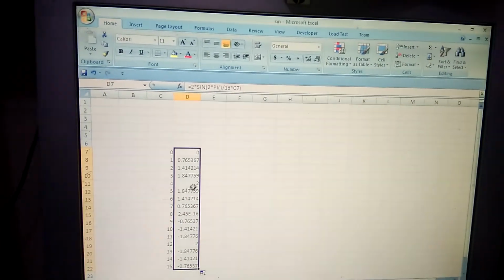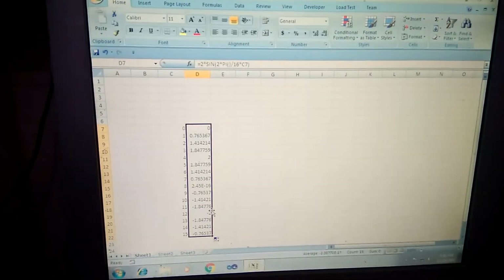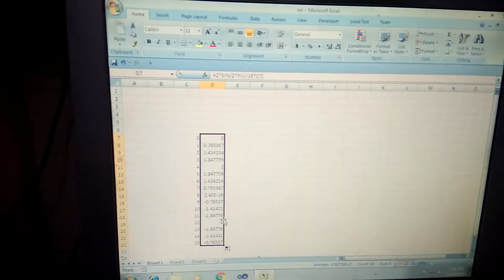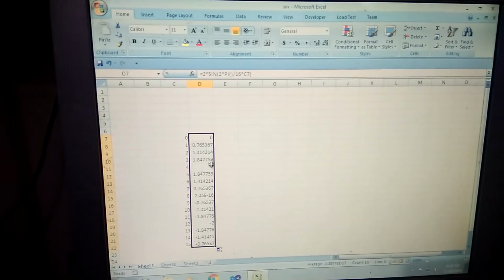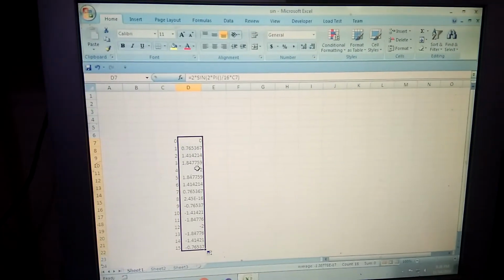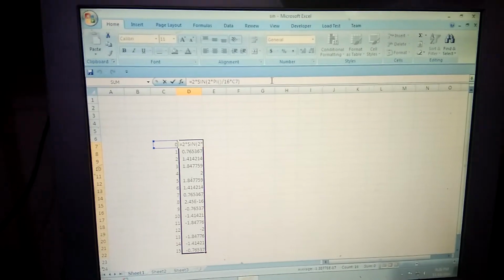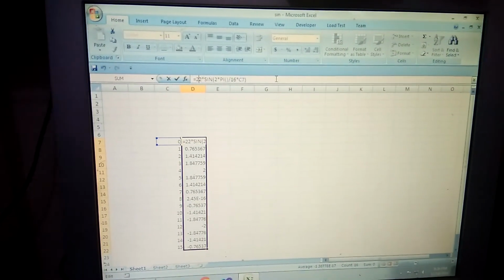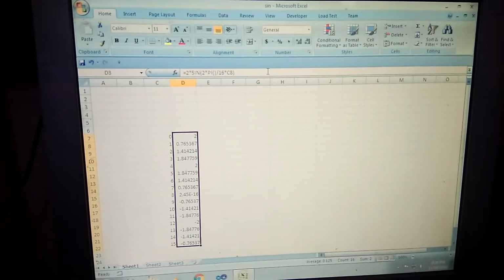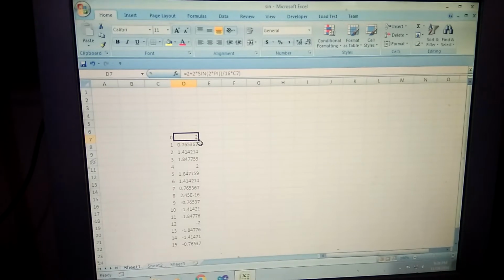Here it gives a sine wave which is both positive as well as negative. Generally, the wave you produce through a microcontroller will ultimately go to a DAC. That DAC works on integer values, and these are decimal and negative values. To convert negative to positive, you simply add a DC voltage of equal amplitude, and you will get all positive values. So this is the equation.